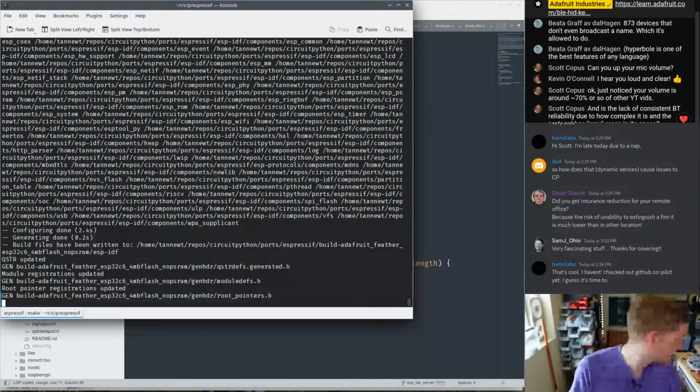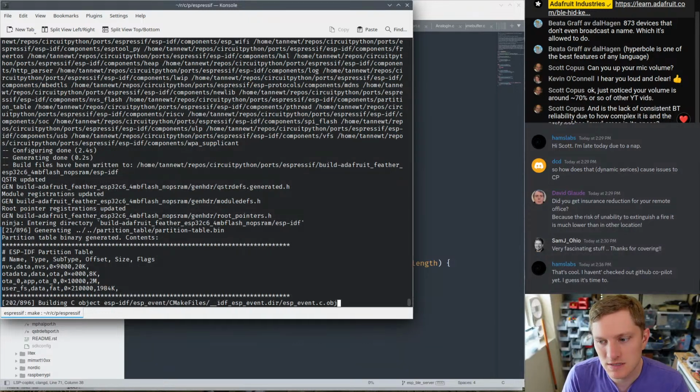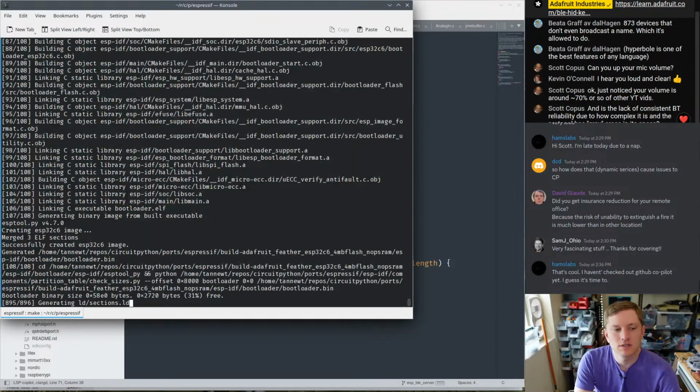And then I could cycle back to the ESP32 as well. See if I'm in any better shape there. But man, it was crashing really weirdly. I'm not sure why. I don't even know if it's my bug. It was safe moding with a watchdog timeout on the interrupts. It makes sure that interrupts aren't disabled too long, like 1.8 seconds. But CircuitPython never directly disables interrupts. It disables task switching, but it doesn't really disable interrupts.